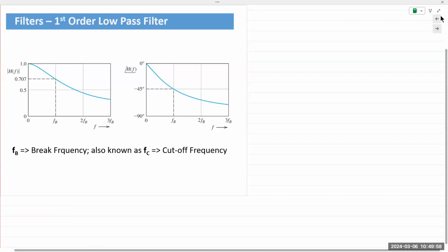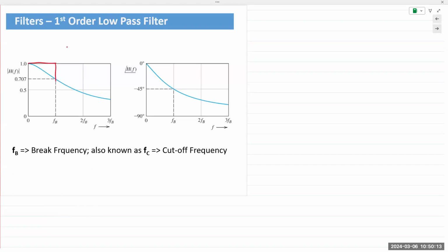All right, any other questions for the low pass filter? Okay, so the behavior of a low pass filter when plotted as a function of frequency would look like this. All right, it has a gentle slope. Ideal filters, of course, we would want something like this, where on the left is pass, and the right is blocked. That is the magnitude of the transfer function H of f plotted as a function of frequency f. Okay, it's the magnitude of the transfer function, and it's a normalized function. Hence, the maximum value is 1.